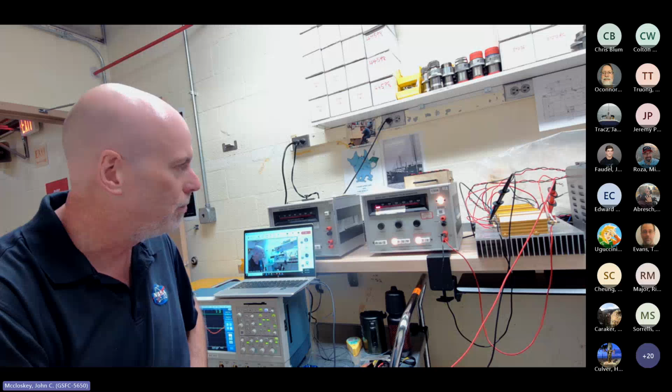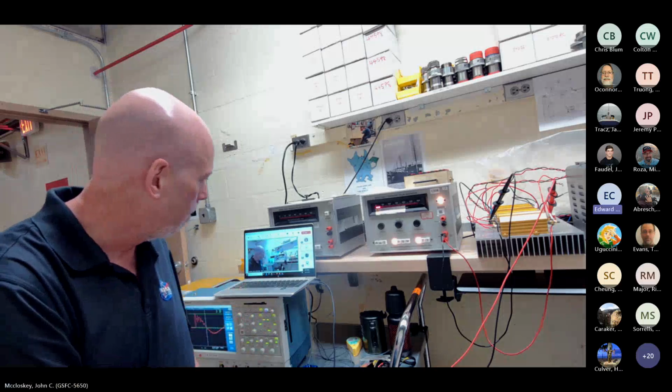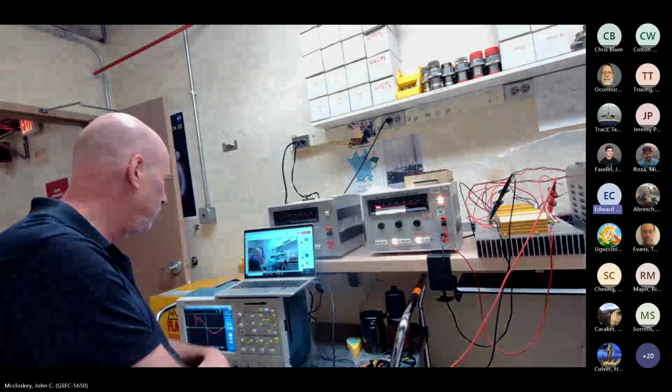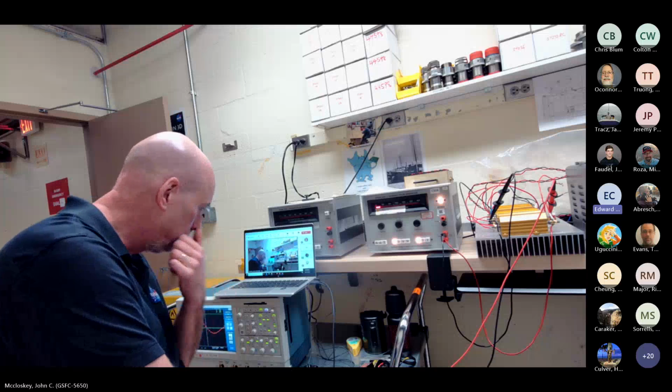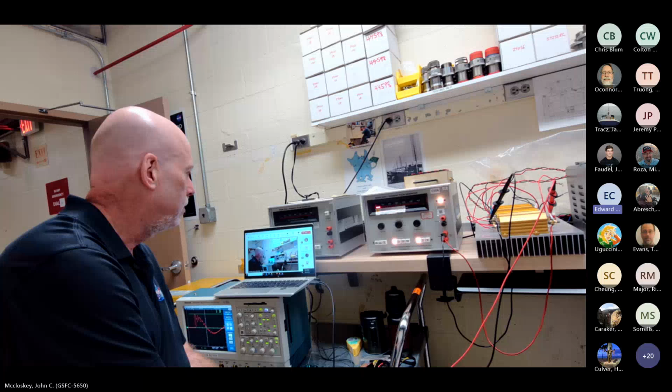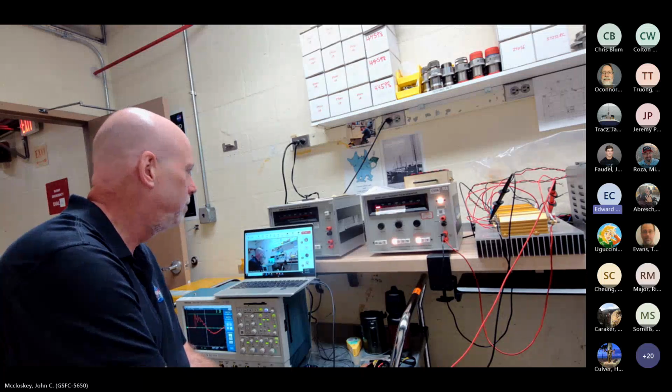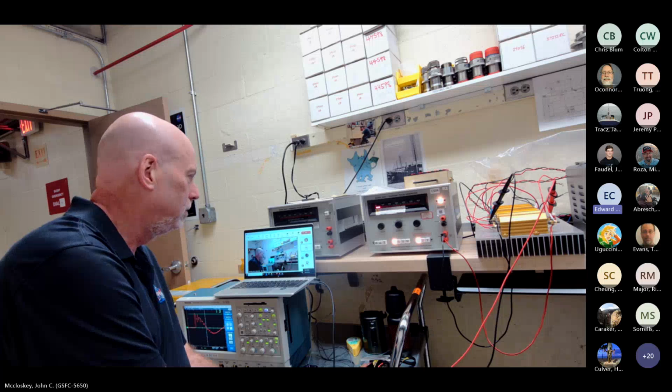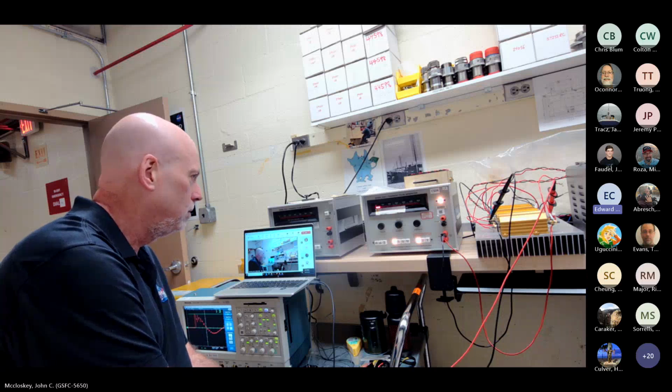Hey, John, if I could add something, my experience with CS06 has not been good, frankly. I was a young engineer building for space station, and our peak voltage, 3 times the bus of 120, is 360. And unfortunately, I had hardware be damaged, which was flight hardware ready to go. It got damaged, and I really learned an expensive lesson that day. So of all the tests, CS06 is the one that really gets my ears up.